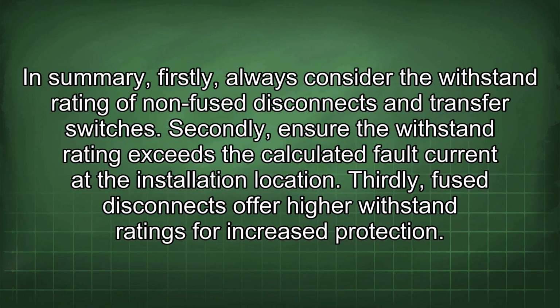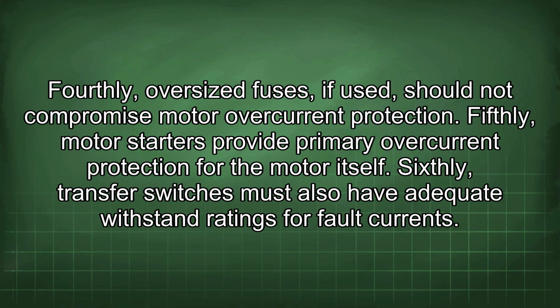In summary, firstly, always consider the withstand rating of non-fused disconnects and transfer switches. Secondly, ensure the withstand rating exceeds the calculated fault current at the installation location. Thirdly, fused disconnects offer higher withstand ratings for increased protection. Fourthly, oversized fuses, if used, should not compromise motor overcurrent protection. Fifthly, motor starters provide primary overcurrent protection for the motor itself.